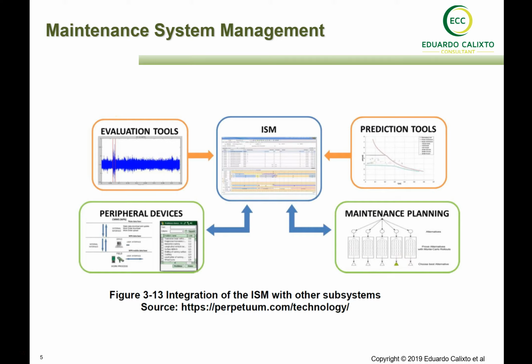There is preventive maintenance based on a schedule that comes from RCM, from RBI inspections, as well as other inspections that are defined for the RBI and set up in a CMMS system at the very beginning of operation in the plant, and later on this plan is constantly updated. So in the end, when such a prognostic health management system triggers some issues based on the sensor detection and predicts the remaining life, such information will also be input as scheduled maintenance and will be part of the maintenance system management.